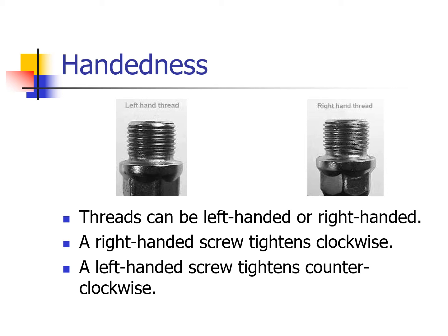The right-hand side of a bicycle has a right-handed screw, and the left-hand side of the bicycle has a left-handed screw. That is done so that as you are pedaling forward, you tend to tighten the pedal in the crank, and so it won't loosen as you're pedaling. I've seen many a person who didn't realize that and tries to turn to loosen and take a pedal off on the left-hand side, going the wrong way and ending up breaking the crank or breaking the pedal. So be aware that there are parts out there.